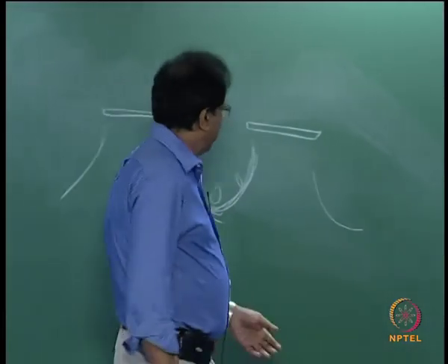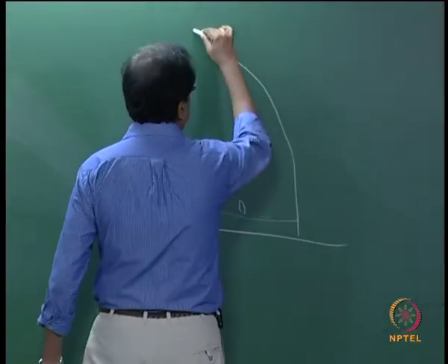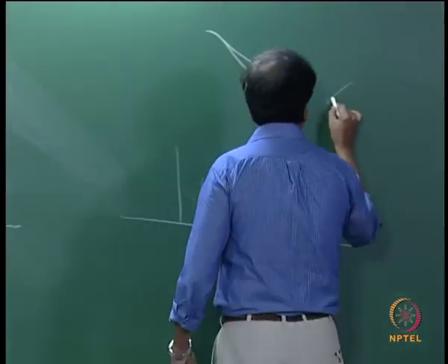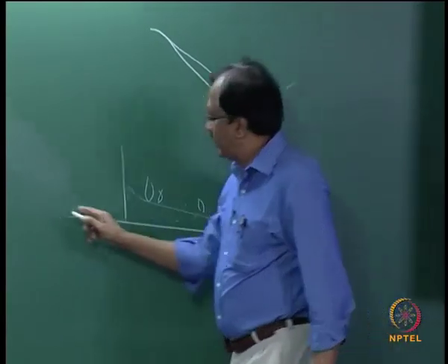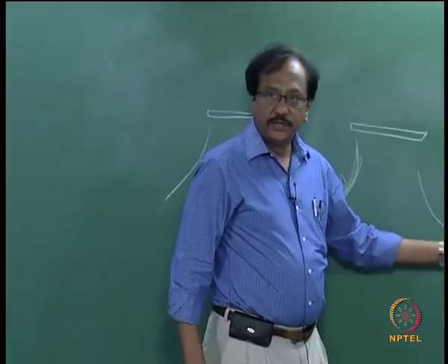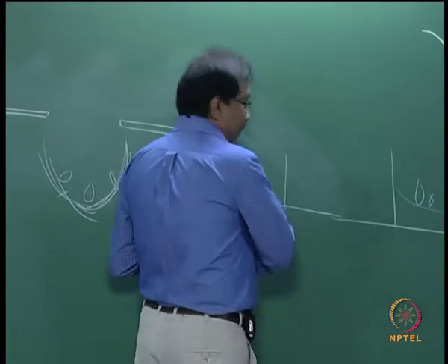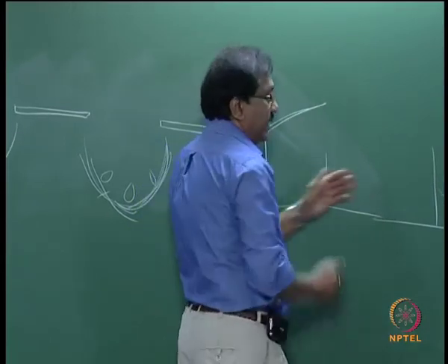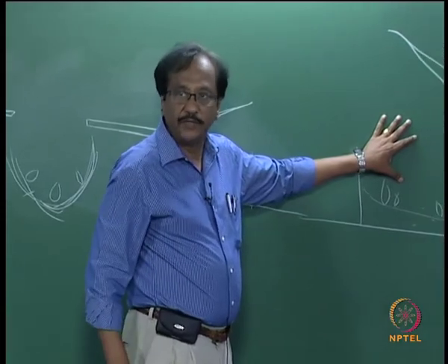Tomorrow if you want, it is not so difficult in this case to extend one of the arms, if the predominant direction is this way, and convert this into a small harbor itself. Instead of considering only 2 or 3 groins, you can add 4 groins and develop this as a major fishing harbor if you want to.